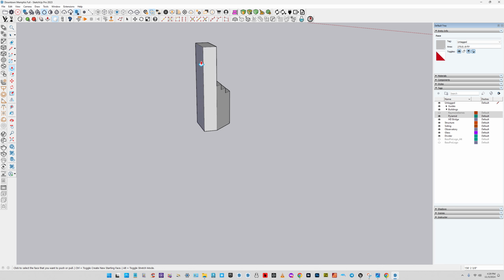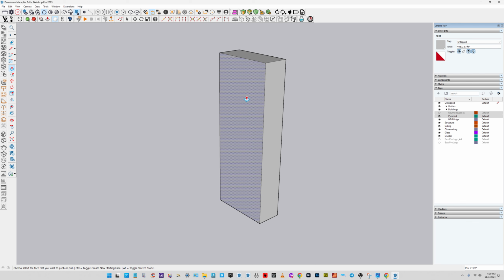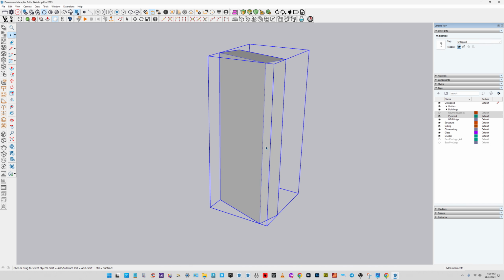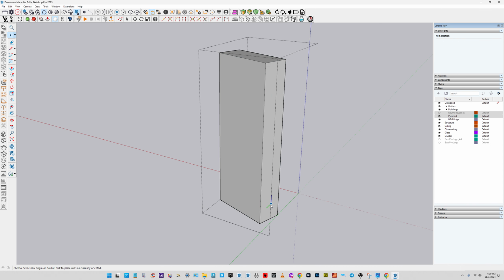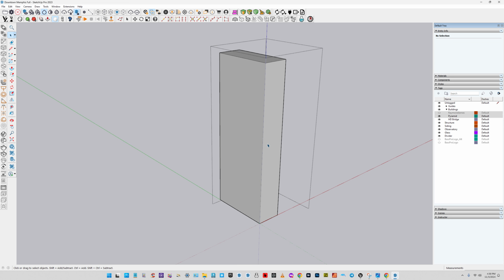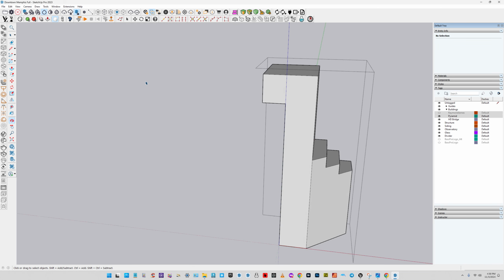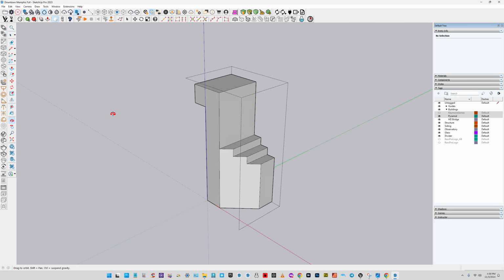and now I'll just do a quick extrude of my asset up here. And you know, let's just say for shits and giggles, we're going to draw a line. First, let me go in here and group this, and then go into the group, Control Shift A to adjust the pivot. And now, if I go in there and draw that line, my axes will be appropriately lined to the faces on my building. All right, extrude this out a little bit. Let's just say for shits and giggles, we're going to extrude that out, make it an L.